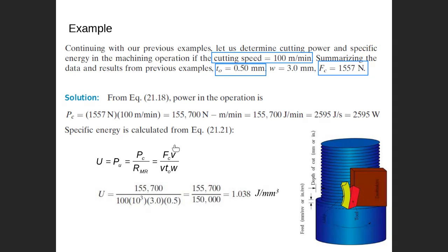If you have VS, you can use the speed triangle and then you get the cutting speed based on the speed relationship with the angle. If they give you the angle and the shear velocity, then you can obtain the cutting speed or cutting velocity based on the cutting velocity triangle. All these things you have to consider and keep in mind while dealing with the problem.